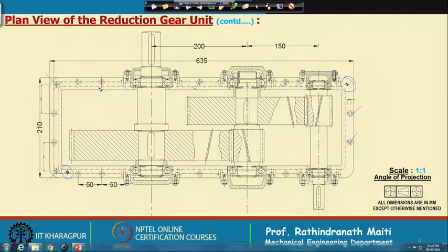Apparently, these are placed about 50 millimeter, here it is a little more, 65 millimeter or so, and near the bearing we have put large size bolt. We will put here M10 bolt. Okay. So, this will be good enough for taking all bearing loads, and we have kept this M10 bolt size of equal size. So, totally required 12 numbers of such bolts, nuts, washers, etc.